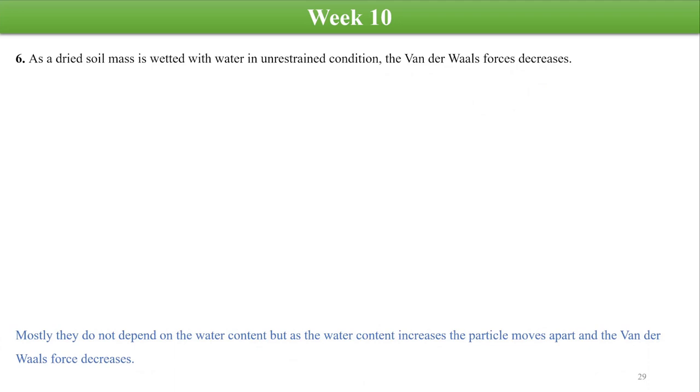Then there is a question that as a dried soil mass is wetted with water in unrestrained condition, the van der Waals forces decrease. Mostly the van der Waals forces do not depend on the water content, but as you increase the water content, the particles will move apart. Therefore, the van der Waals forces will decrease. Van der Waals force basically depends on how close the particles are. So as you increase the saturation in the soil, the water will infiltrate into the pores, and this will increase the distance between the particles. So this statement is correct in that sense.